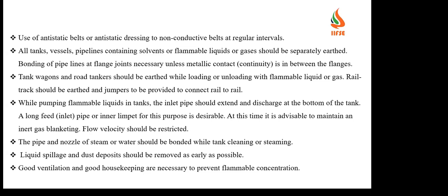And rail tanks should be earthed and jumpers provided to connect the rail tank to the rails. So in a rail track, in bigger industries, they get wagons on the rails. In those cases, we have to connect these static jumpers for the elimination.